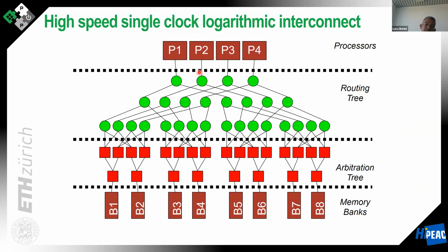How can we do that? Multi-ported memories, when we have more than a couple of ports, are super expensive and at the circuit level are not a viable proposition. So instead of using multi-ported memory, we emulate multi-ported memory using a single-ported memory in a multi-bank configuration.